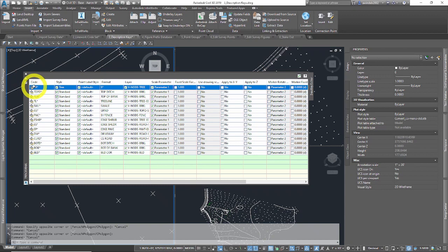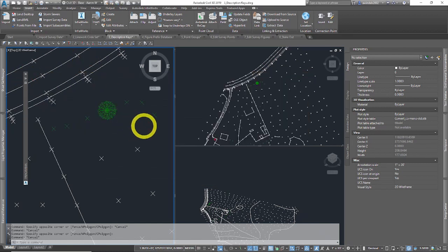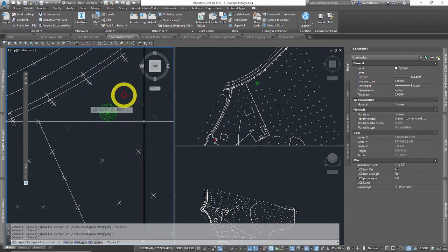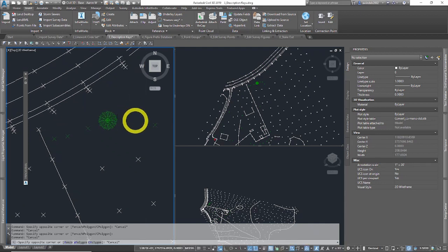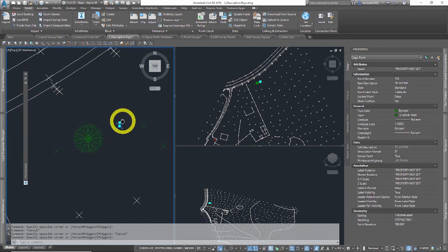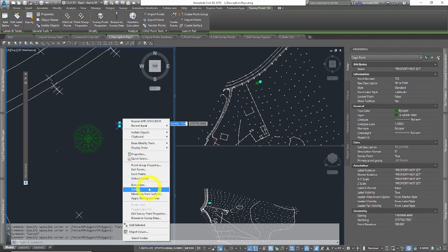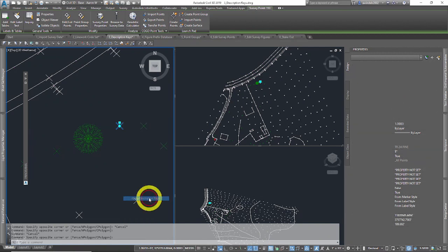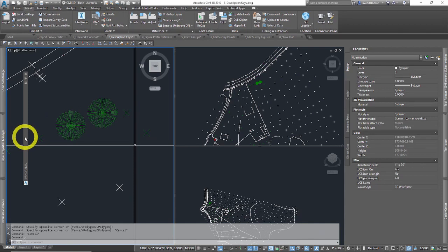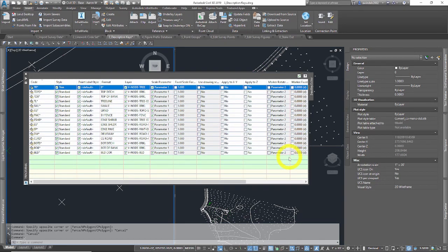And let's cascade. This is in my description keys editor that I went to a little earlier. Let me cascade that down. Now let me do one at a time. I'm losing my crosshairs. Another awesome AutoCAD glitch going on. And I will apply description key just to that one. There we go. That time it worked because I changed it in the description keys here.